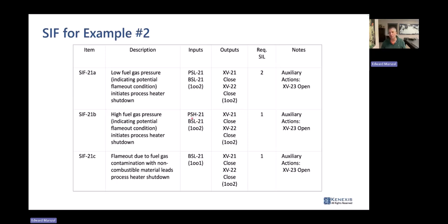where you're putting in more fuel than you can burn, but not so much that the flame goes out, and now you've got a flammable atmosphere with hydrocarbons, carbon monoxide loading up your firebox. And in that situation, if you give it air instead of cutting back fuel, you will cause the firebox explosion that you're intending to protect against. So right there, depending on how you actually define the hazard, you might not want to include this flame scanner.